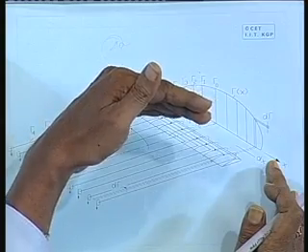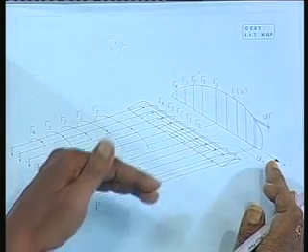Now, if you have to do a propeller design, you can now see that we can represent the propeller blade by a line with a varying circulation, and that line will shed a trailing vortex sheet, and we can do the calculation by representing the propeller blade by a line which is a lifting line, because this will generate lift. So, this is called the lifting line theory. This is the most modern propeller design theory on which propeller design is based, called lifting line theory.